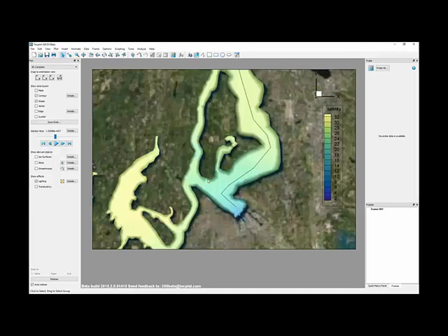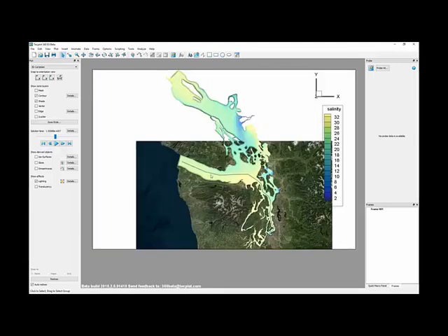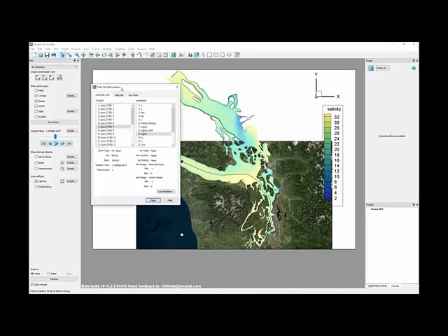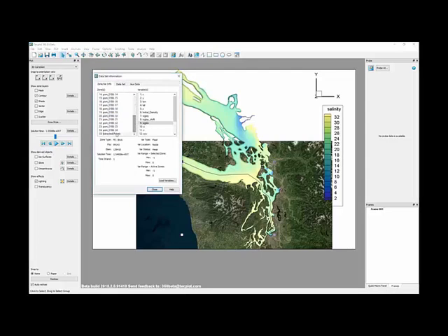I'll just do Control F to do a view fit. And now what I'm going to do is extract these points to a new Tecplot zone. So let's go into the dataset information dialog and show you what we've done here. By doing that extract, I now have a new zone that we've created. It's I-ordered, so that means it's just an array of data. And a Python script that I'm going to execute is going to use the XY locations to define the path